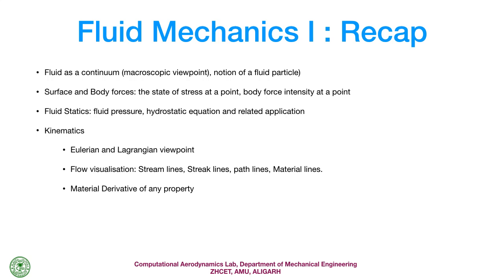Now if you apply this on velocity, it gives you capital DV by Dt. It gives you the acceleration of the fluid particle. One part gives you the local acceleration, that is del v by del t, and the other part, say u del v by del x plus v del u by del y, gives you the convective acceleration, or the acceleration due to space variation.